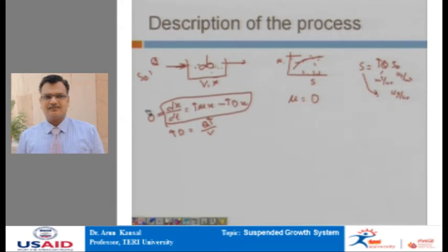Rather, on the other hand, we have seen that Monod's equation becomes asymptotic towards the x-axis, which means that after a certain stage of food supply, there is no net increase in the growth rate. So, in fact, if we increase the discharge rate beyond a certain level, we will rather have a net decrease in the bacterial density. If I plot a graph between dilution rate versus bacterial density, which I am denoting with the symbol BD, there is a fast washout of the microorganisms.